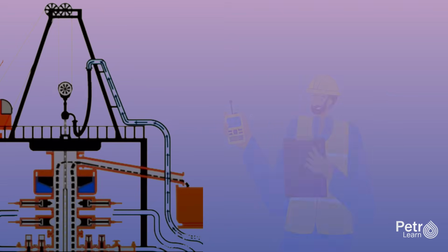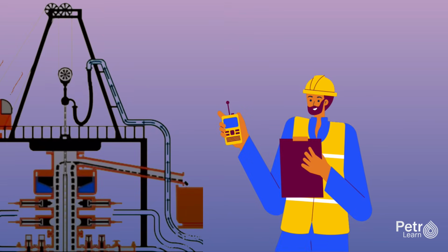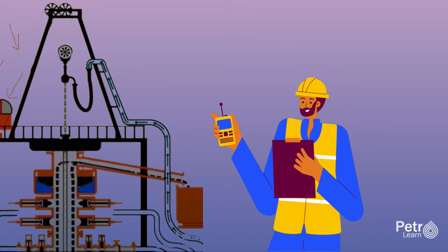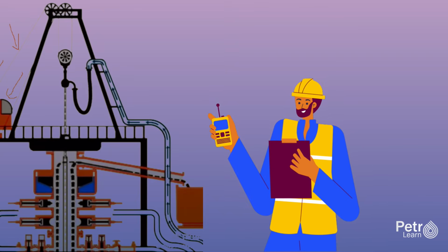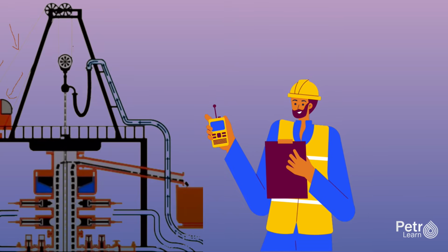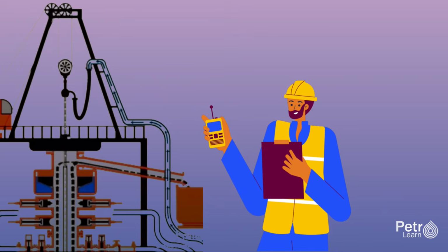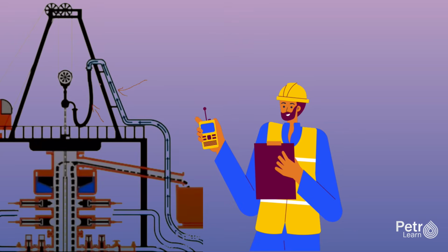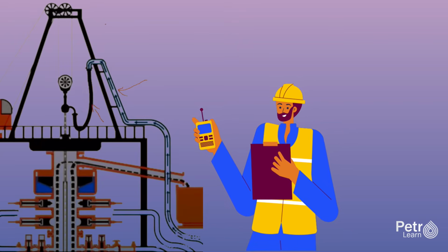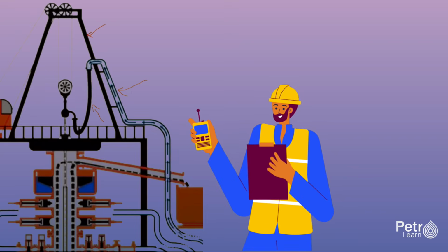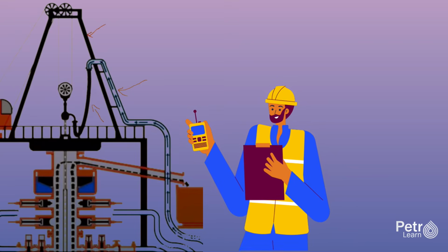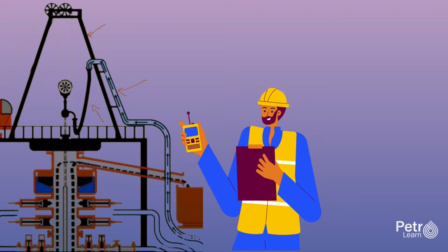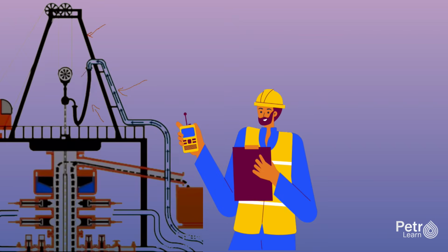A mud engineer is on site continuously monitoring and adjusting mud properties. Key properties measured include density or mud weight, measured in pounds per gallon or ppg, viscosity, which affects how well it carries cuttings, gel strength, which is how much the mud solidifies when circulation stops, fluid loss, which indicates how much liquid will escape into permeable formations, and pH, which affects corrosion rates and chemical stability. The mud engineer uses laboratory equipment in a mobile unit to test these properties every few hours and adds materials as needed to keep everything within specification.